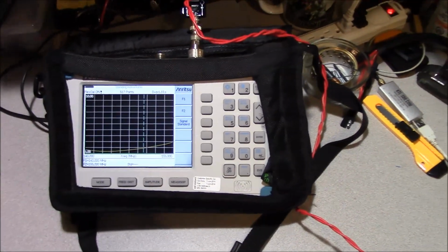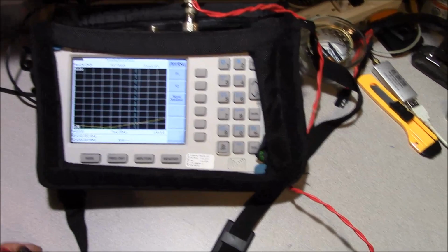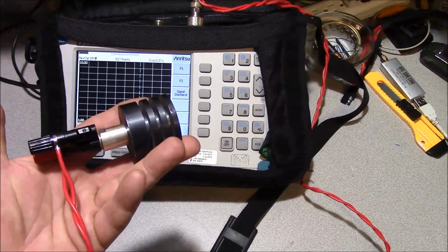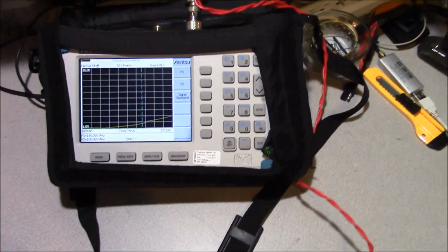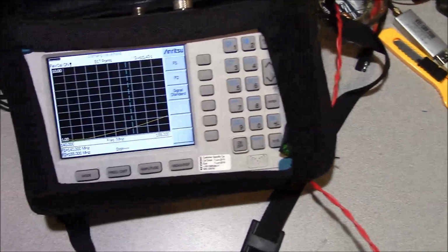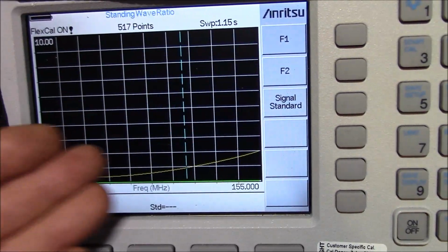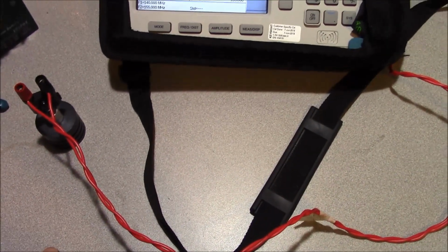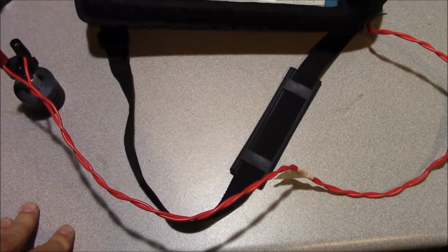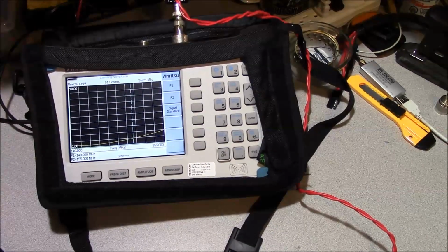The following formulas presented herein have been kind of an amalgamation of my own experimentation here, utilizing this 50 ohm dummy load to simulate an antenna, and of course our cables under test utilizing a couple of binding post adapters. And basically we're just sweeping this line here and noting the changes that occur based upon frequency versus wavelength of the feed line, and then trying to calculate what the velocity factor of the line is, and we'll get into that later on. And the information gathered from Module 10 of the Naval Electrical and Electronics Training System.